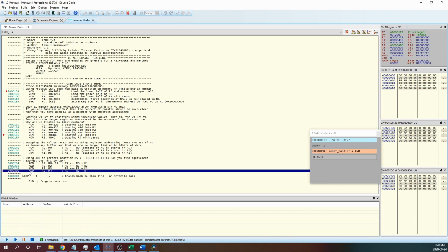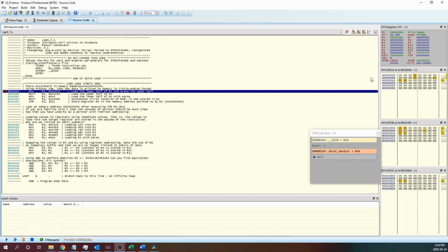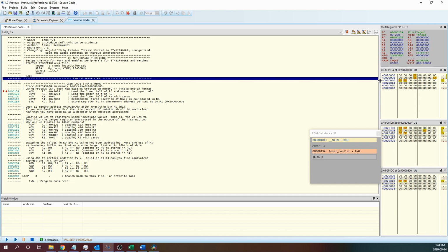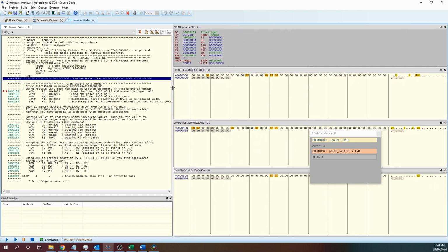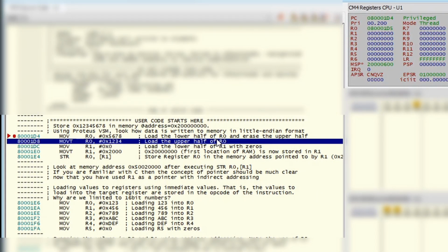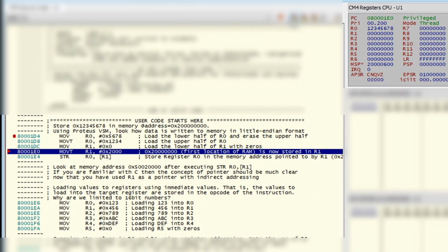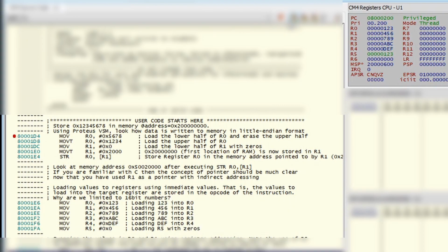Please notice that some debugging buttons may not work as intended. Why? Well, when we program in assembly, it's harder to tell where a function call begins or finishes. You will know in a future lab, but the .elf file will not contain that information. The debugging buttons will work well for languages such as C. During any debugging session, we will watch the CPU registers. Most registers are visible through the register panel. When we step through the program, we can see the registers changing value. That's it for the debugging introduction using the Source Code tab.